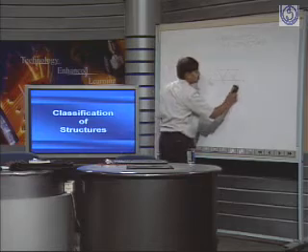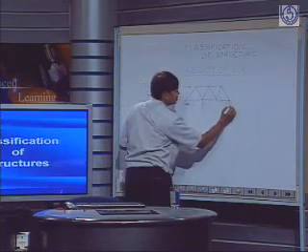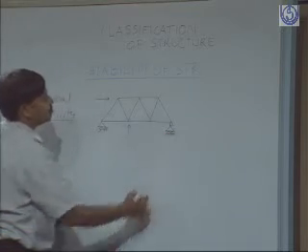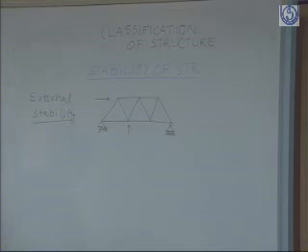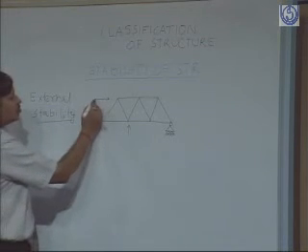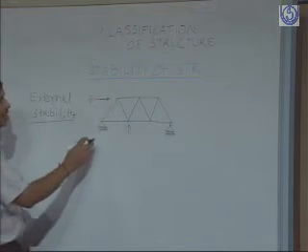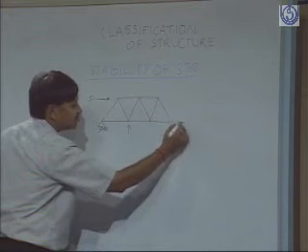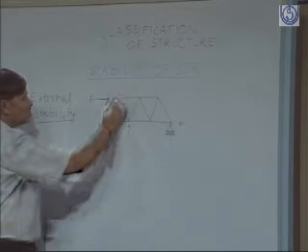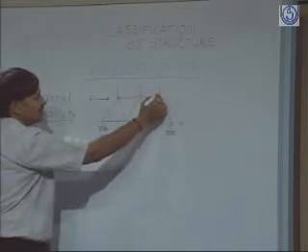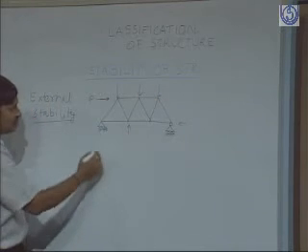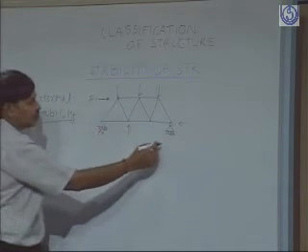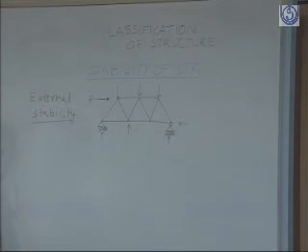This is not a roller support. We again put a roller support here. So what will happen if you put a force in this direction? The whole truss will move in this direction because there is no restraining force in this direction, whereas it can take loads in these directions, because in this vertical direction the roller support is there, so it can restrain its movement.